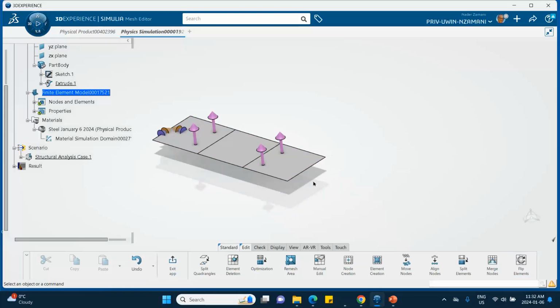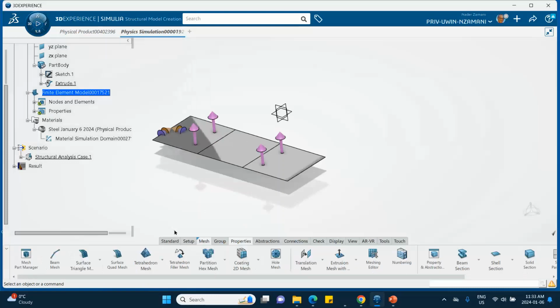One thing you should not forget is exit. Because if you don't exit, it doesn't recognize that there was a switch here. And when you try to run it later on, it's not going to give you a warning, but it says this surface cannot be found, this pressure cannot be found, because you did not exit properly. Exit. Now we go back to our scenario.